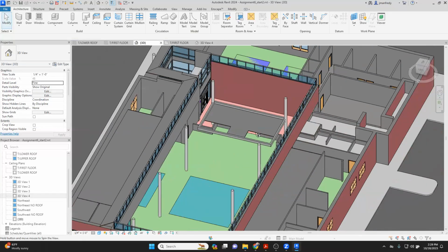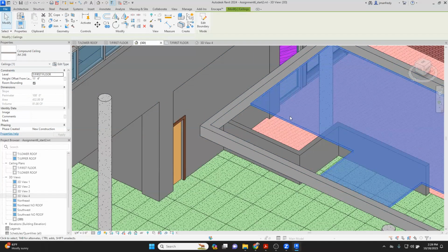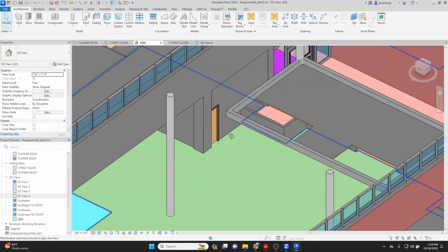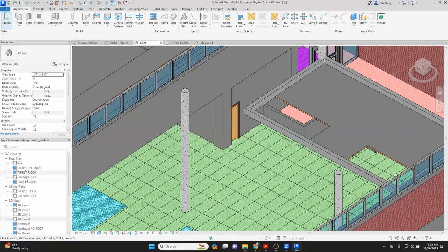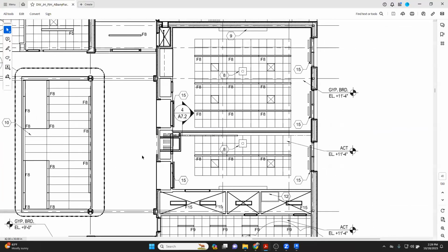And if I take a look at it here, there it is. And you can see the problem here. This guy's too thin. You need to make a little tiny wall along these edges here to fill that gap. Or maybe make this ceiling really, really thick. But it's going to make it thick everywhere, right? So everywhere I used it, it's going to be 14 inches thick, and that's not going to be right. Maybe you want to duplicate it. You guys can decide how to put a little panel right here to close off this little opening here. It should be traced on both sides. In the ceiling plan, there's another little thing here. You can see in the product, it looks like this thing's about.